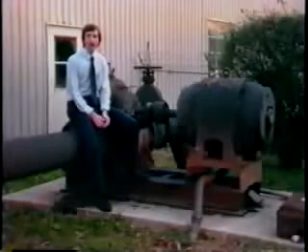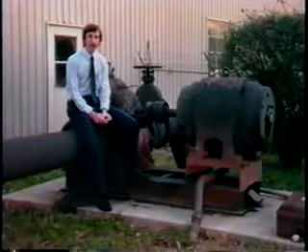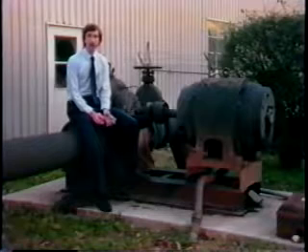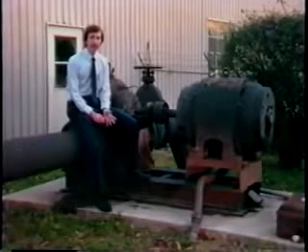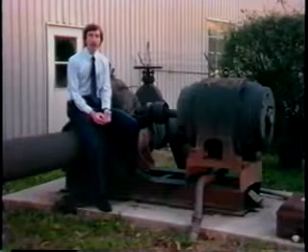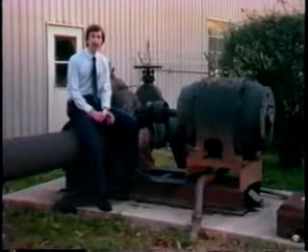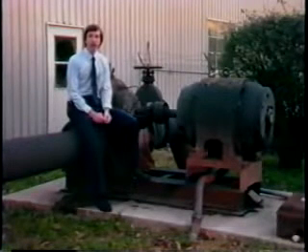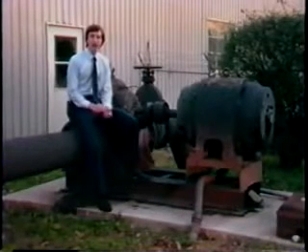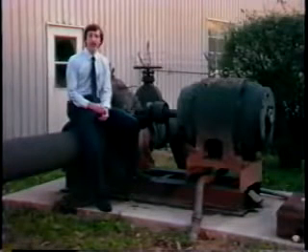You're wondering why I'm leaning up against this pump when we're really talking about hydrant flow tests today. Well, as you know, what's happening at pumping stations has a lot to do with the resultant tests. Yet you can look at the results of hydrant tests run by some people and there's no indication of whether pumps were on or how many pumps are on or which pumps were on. This is unfortunate because it renders the results of these tests less useful for calibrating pipe network models. What you need to do is know which pumps are running when you're conducting the test. This is very important information and it's very easy to get.